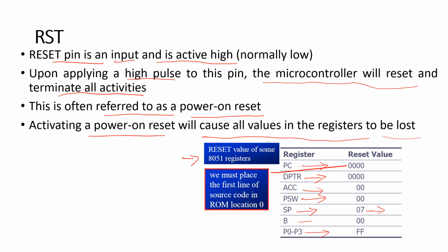Ports will be made FF, because by default the ports act as output ports. If we want to use ports as input ports, we need to program them. So these are the actions which take place when we perform reset, or press the reset pin of the 8051: default register values of 0 and stack pointer with 07.